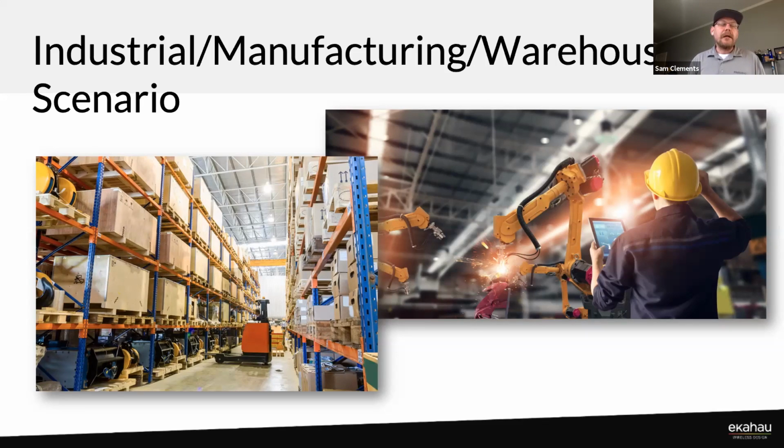I would say that in those environments, it becomes really, really critical to understand how that RF looks, because when you talk about providing RF coverage at that 1 meter off the ground mark, or you're going to hold the device, or maybe 1.5 meters where the forklift computer is or whatever, you really want to make sure that that AP is going to be up where it is so that you understand what the resulting RF is going to be like on the ground, whether you're pointing a patch at the ground or you're using a low gain Omni or a high gain Omni, depending on your application.